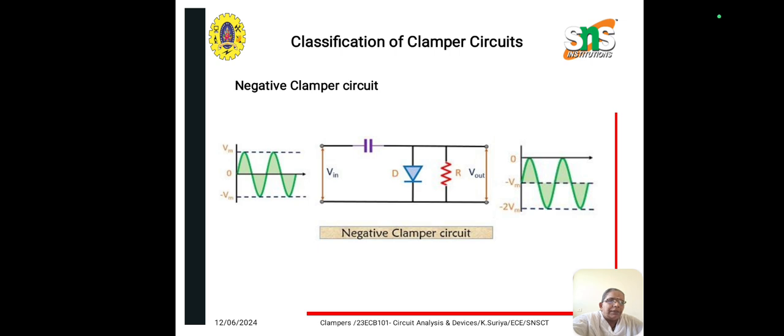When negative half cycle of the AC signal is applied, the diode now becomes reverse biased. This allows load current to appear at the output of the circuit. So now this non-conducting state of the diode discharges the capacitor. So at the output, a summation of capacitor voltage along with the input voltage is achieved.